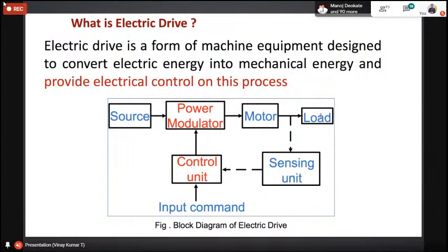So that is to change the position or to shift the luggage from one point to another point. Here let us assume that 12 Newton meter torque is required. So the motor torque should be greater than the load required torque, right? The load requires 12 Newton meter, but the motor capacity should be more than 12 Newton meter. Like that, you need to select the motor.